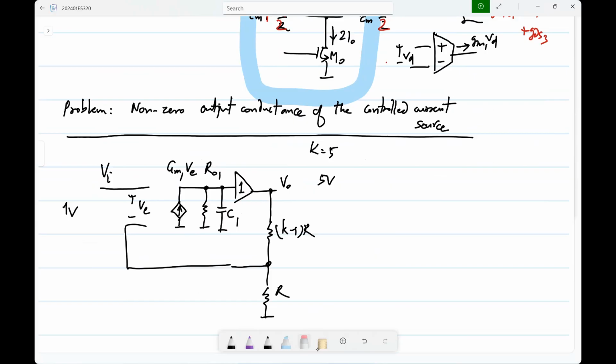When you have DC, I mean constant signals and steady state, it means that the capacitor currents are zero, inductor voltages are zero in any circuit. That's how you can simply open circuit all the capacitors, short circuit all the inductors, and do DC analysis, right? So it won't come from the capacitor. So where does it come from?